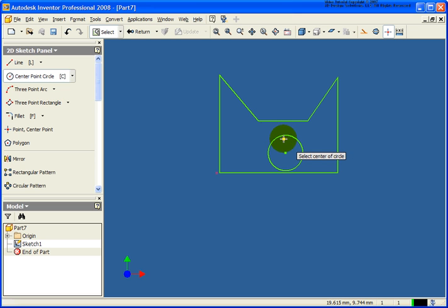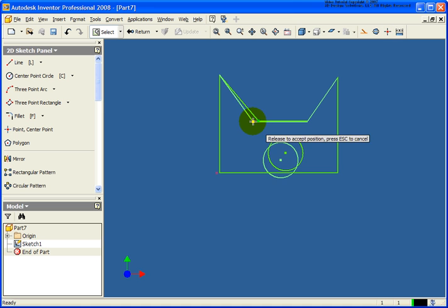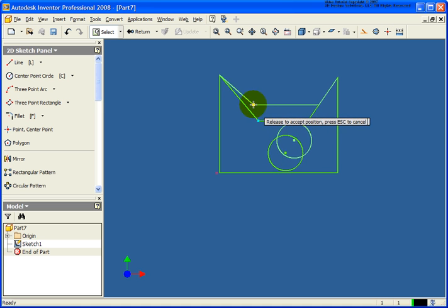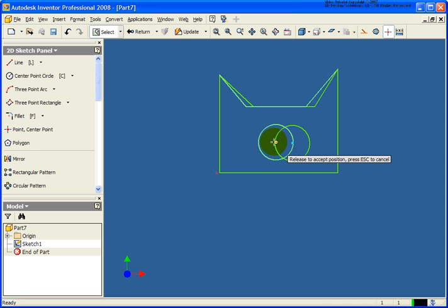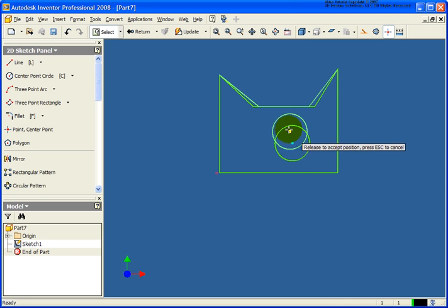of those two lines. So now I'm just going to press the escape key, and let's talk a little bit about dragging. So now as I grab that point and grip edit that, which is very familiar to AutoCAD users, the circle is staying exactly at the theoretical intersection. As well, if I move that circle, the lines move. So there's a definite relationship that is tied to that.